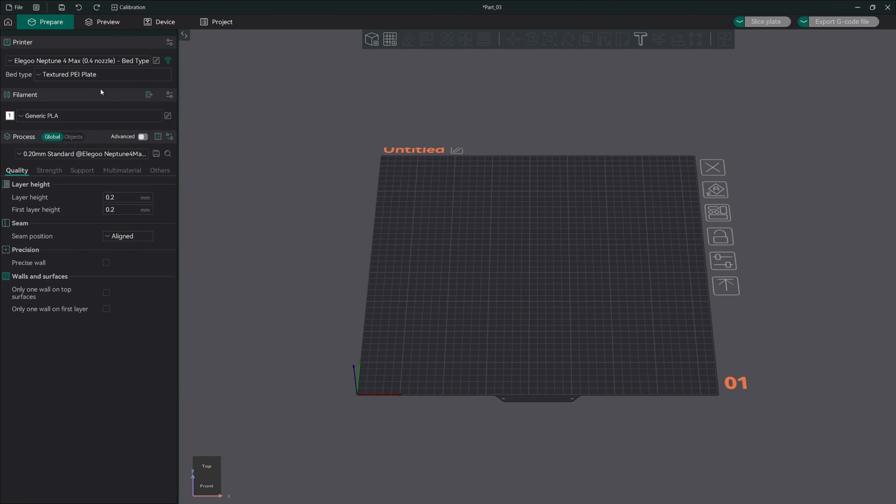The great news is that with version 2.3 of OrcaSlicer, it has all been drastically improved. First up is our Add One Filament button. If you click that, it will add another drop-down filament below. This is something that you would use if you had an AMS from Bambu or an Ace Pro from Anycubic. There are many multicolor systems from many different manufacturers. Once you add a second filament, the ability to remove filaments will appear right here.